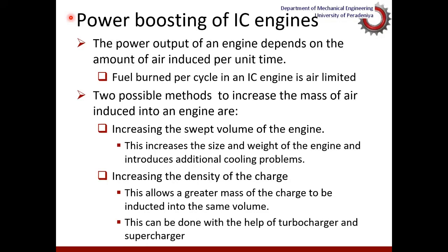One is making the engine larger, that is increasing the swept volume or the displaced volume. And on the other hand, we could increase the density of incoming air. So the focus in this particular discussion is more or less on increasing the density of incoming air so that we could burn more fuel and produce more power. The devices that we use for this increase in the density of incoming air are the turbochargers or a supercharger.